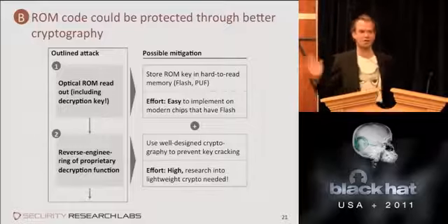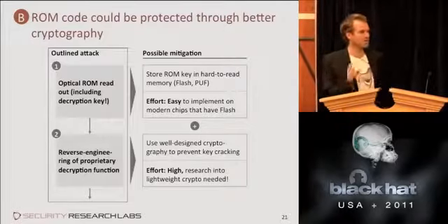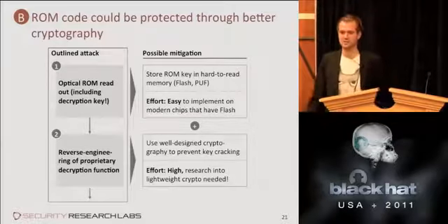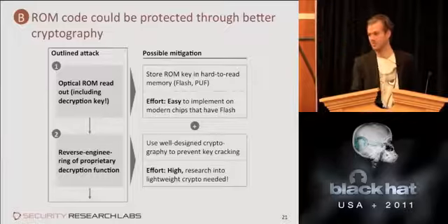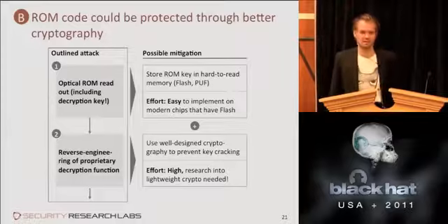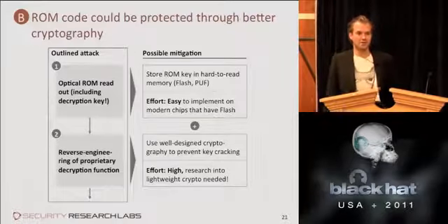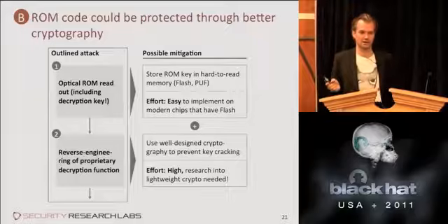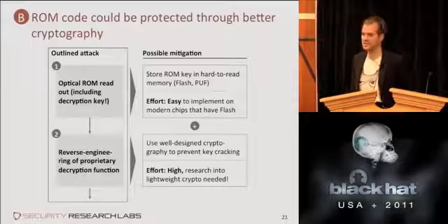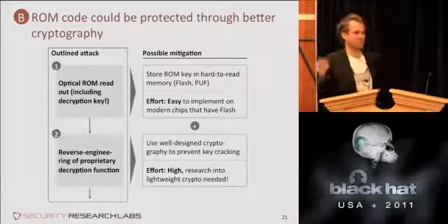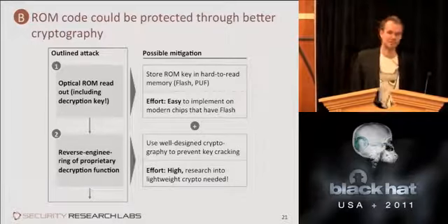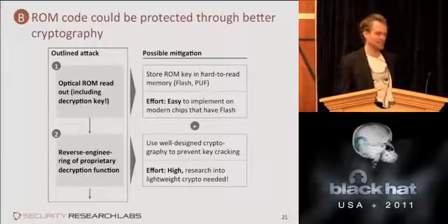So this calls for more cryptographic strength, but in a world where no cryptography has been built yet, one clock cycle block ciphers, right? So this is a research challenge really for everybody to come up with more lightweight block ciphers that, given a little bit of known plaintext, can still cover up the key in little area. It doesn't have to be AES grade. There'll only ever be a certain amount of plaintext. There'll only ever be a certain level of incentive. Nobody wants to break this as badly as they want to break some AES keys.